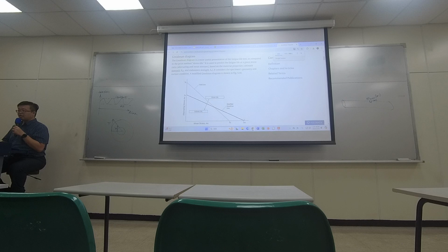The dark straight line is the Goodman. Sometimes people even call it modified, but it's the Goodman. The combination of these two often is called modified Goodman. But anyway, people tend to use different names in different areas, but concept-wise it is the same. Goodman is more conservative for amplitude, but more aggressive on the mean part. And these are the two models.